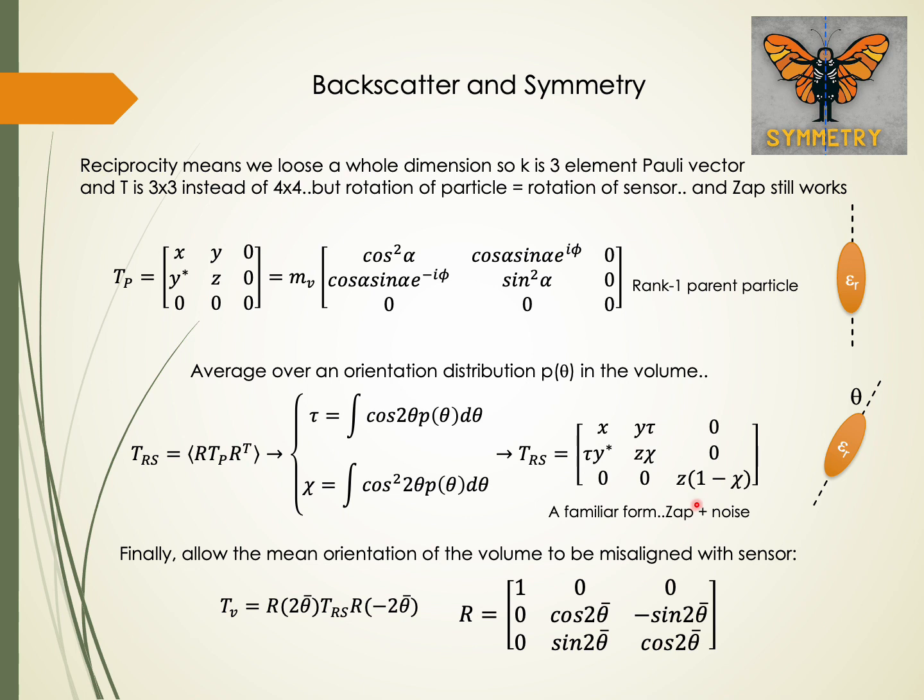And one implication, in fact, is we can simplify it even further, and it often is simplified, because all these parameters, the x, y, z's, and taus and chi's, are too much for many radar applications. And so there is a desire to find a simplified version of it, and that extreme simplified version is when we insist not only do we have rotations, but that this matrix remains invariant to any such rotations, so that we don't have any orientation effects at all in the distribution. That's called azimuthal symmetry, and let's go and take a look.